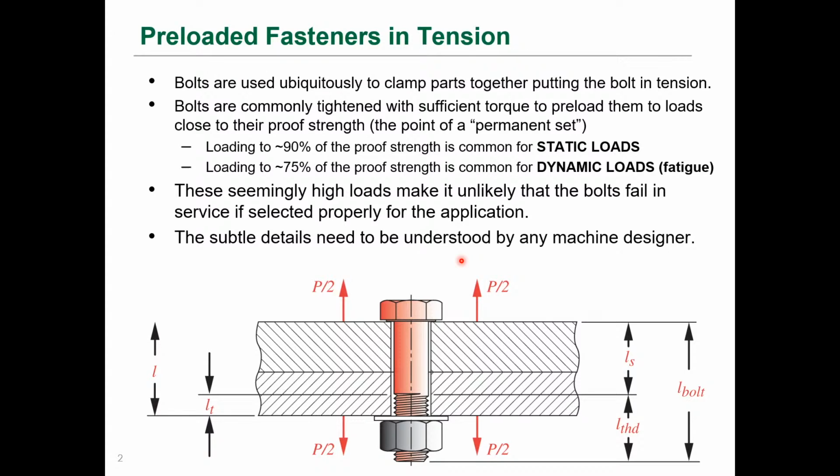These seemingly high loads make it unlikely that the bolts fail in service if they're selected properly for the application. So it's actually very important to make sure that the bolts are installed to the right load so that they are used as they were designed to be used. So these subtle details are really necessary to be understood.